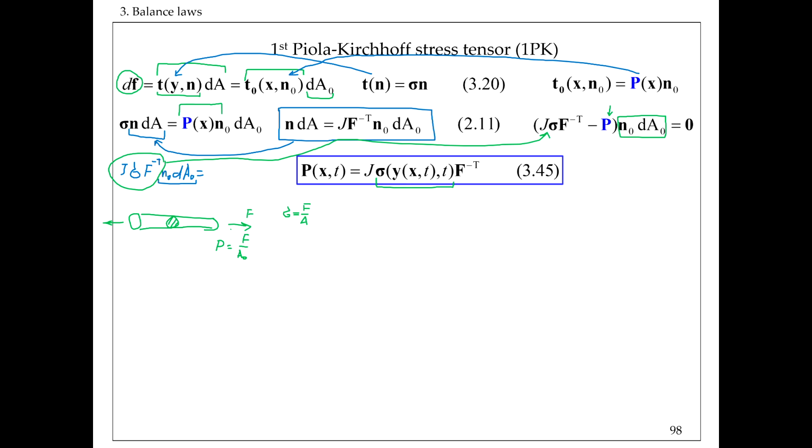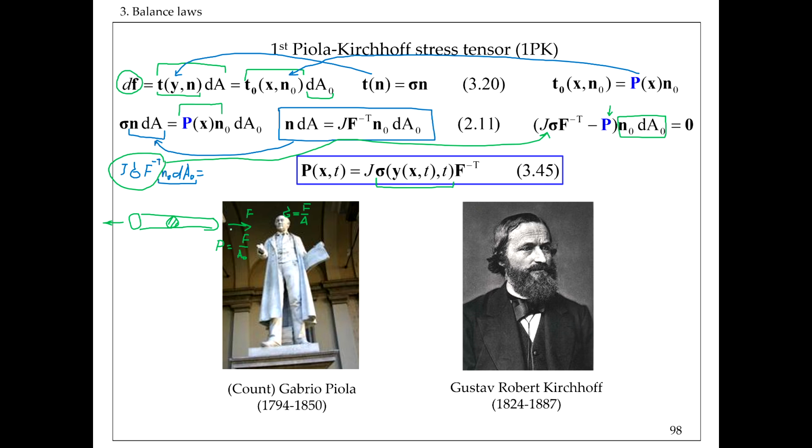In a simple experiment of a uniaxial tension. Right, so unintentionally we have this formula for the Piola stress, and these two phases ended up in our important measure in nonlinear elasticity, or mechanics of soft material, the Piola-Kirchhoff stress. In some literature, especially those taught by Italians, you would probably just call it the Piola stress tensor rather than Piola-Kirchhoff.